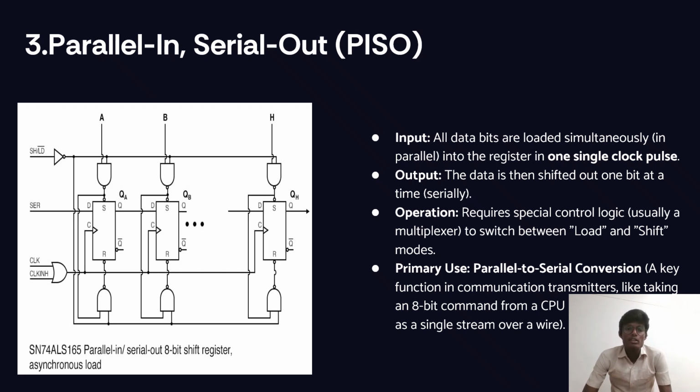This is the representation of the SN74LS165, a parallel in serial out 8-bit shift register with synchronous load. This is the logical design of parallel in serial out. We have the input, output, and operations, and the primary use is parallel to serial conversion.